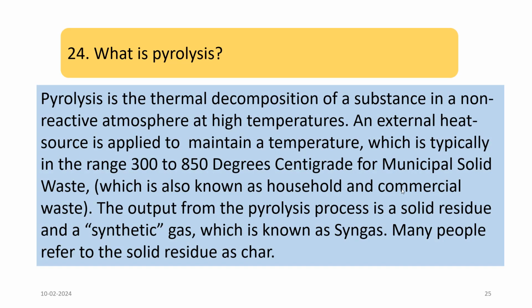Pyrolysis is the thermal decomposition of a substance in a non-reactive atmosphere at high temperatures. An external heat source is applied to maintain a temperature typically in the range of 300 to 850 degrees centigrade. The output from the pyrolysis process is a solid residue and a synthetic gas or syngas.